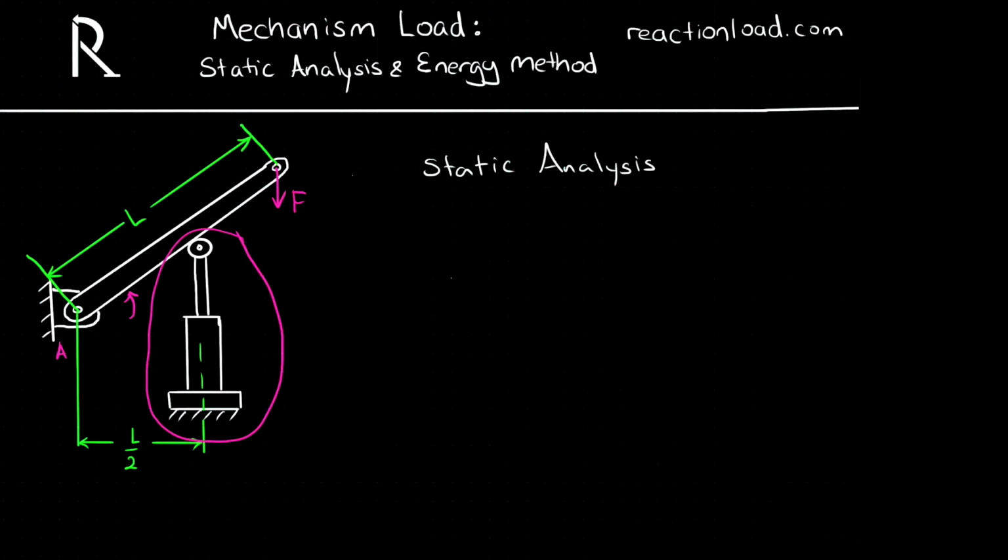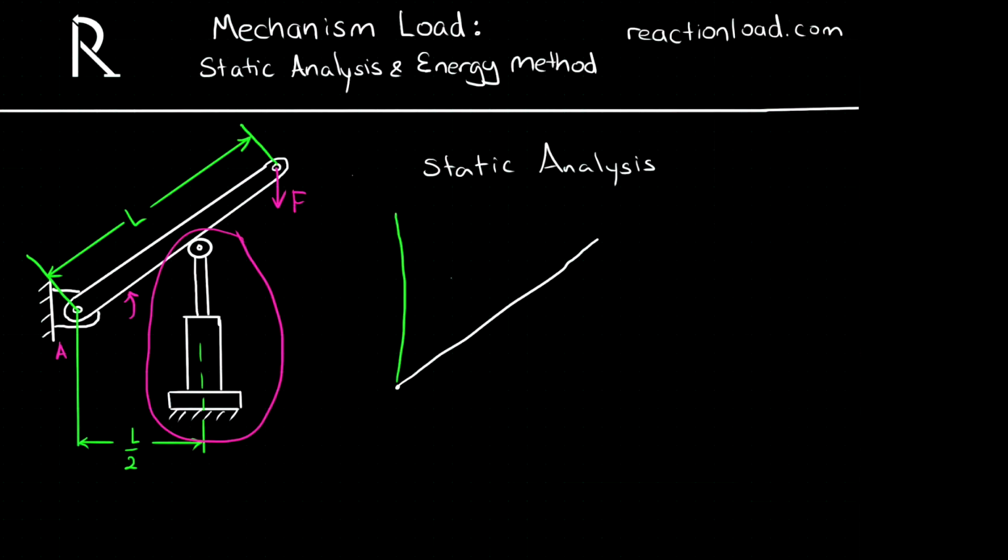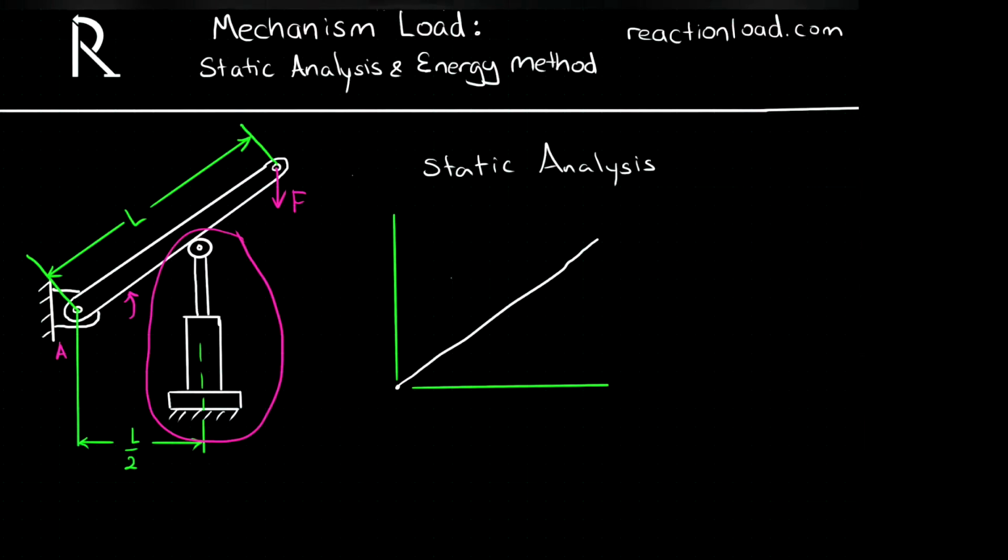Okay, so as always with the statics analysis method, we start with a free body diagram. So let's draw that up now. We have a line to represent our lever, and let's draw in the geometry components. We can represent the rotation of the lever by the angle alpha.